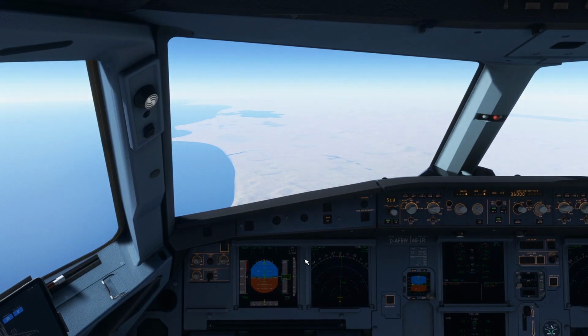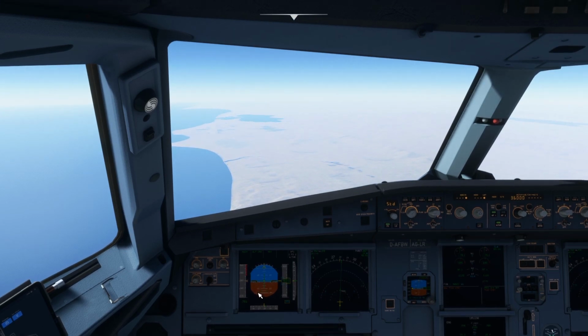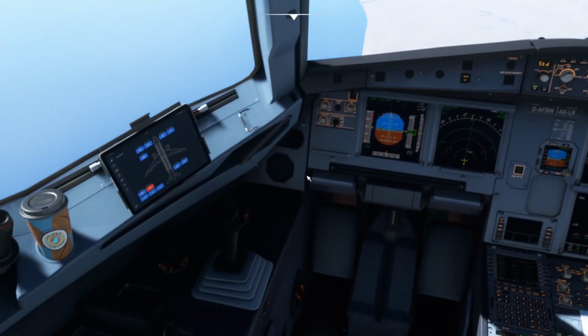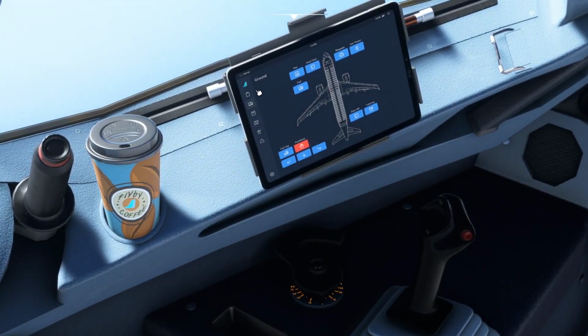Let the autopilot decide the speed, and while you are descending, the autopilot will again, below 30,000 feet, change the speed from Mach to knots. So that's it. Right now we are going at a cruising altitude, and in the tab you can see the map as well.